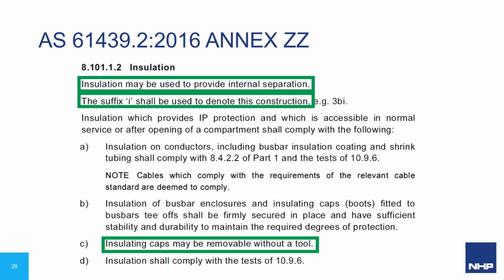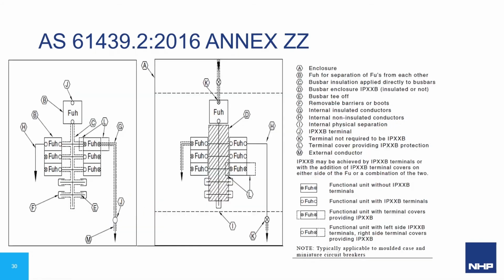When utilizing insulation to separate parts, we must add an I to our form to stipulate this, e.g. Form 3BI. Of course, we can use both insulation and housing at the same time and commonly do. A good example of this would be Form 4AIH.